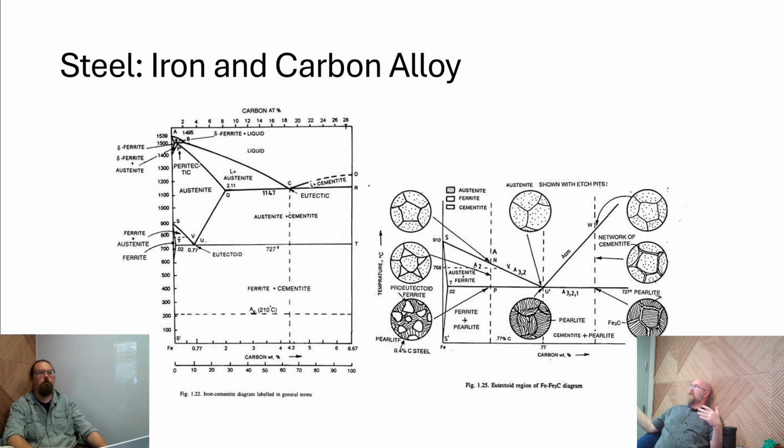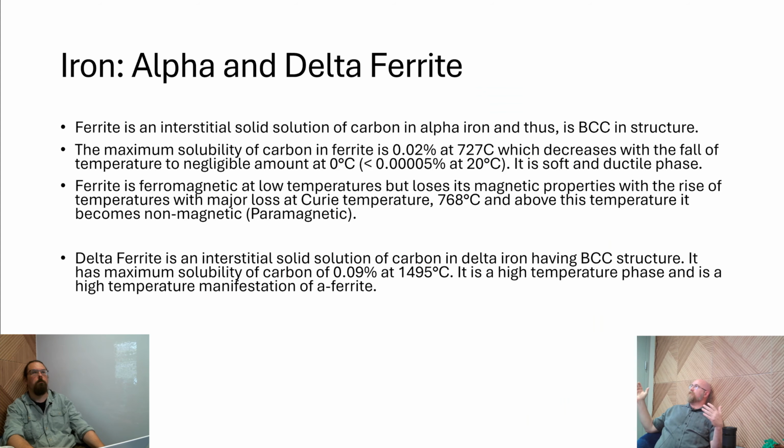Then go on to the next slide after that, which is also about ferrite. It's an interstitial, and this is the reason why it doesn't behave exactly the same as a BCC structure when we're talking about a pure crystalline structure. It is actually an interstitial phase of carbon in an iron structure. So carbon is injected into this BCC formation, and it's the guy in the middle.